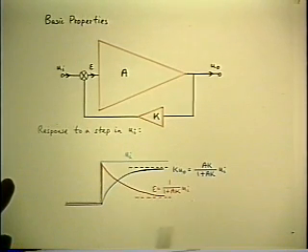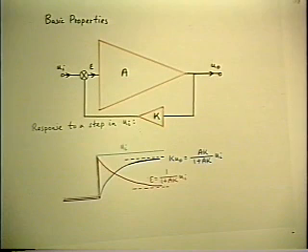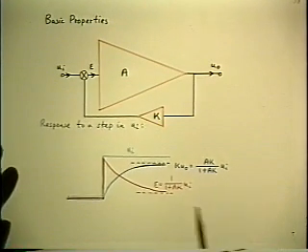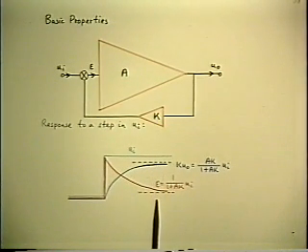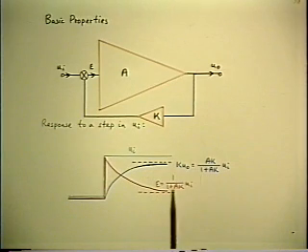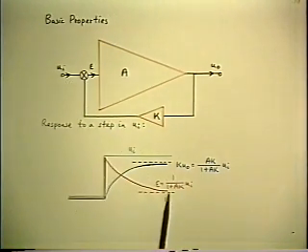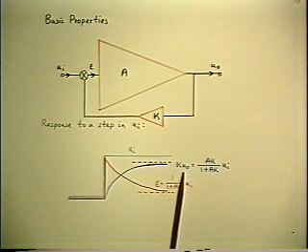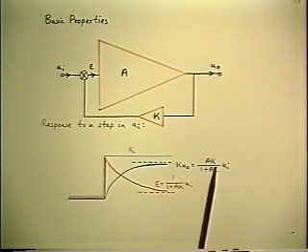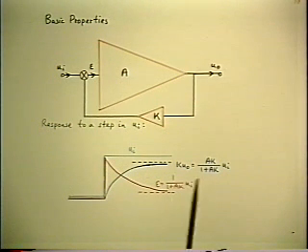That's steady state because it doesn't have to readjust anymore. And so you can label the final asymptotes with the steady state solution, which is that the error signal is equal to the input signal divided by 1 plus AK, and the fed back signal is basically the input signal minus that.